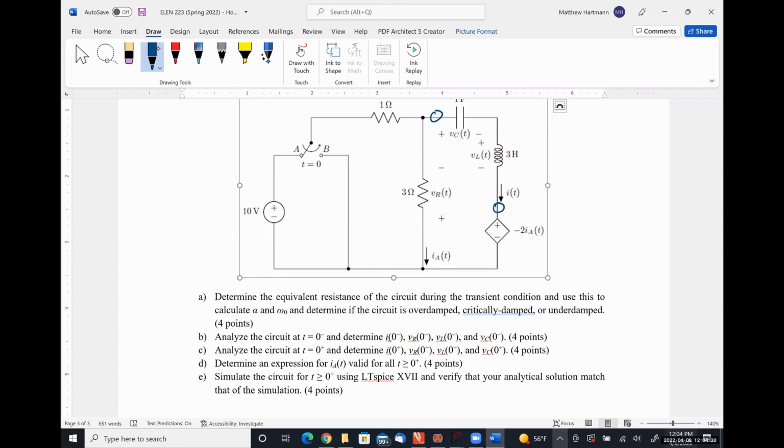And the voltage VC is going to be 7.5 minus 5. Right, if IA is 2.5, negative 2 times 2.5 is minus 5. So we have minus 5 up here, 7.5 here, 12.5 volts, excuse me. So VC at 0 minus should be positive 12.5 volts.